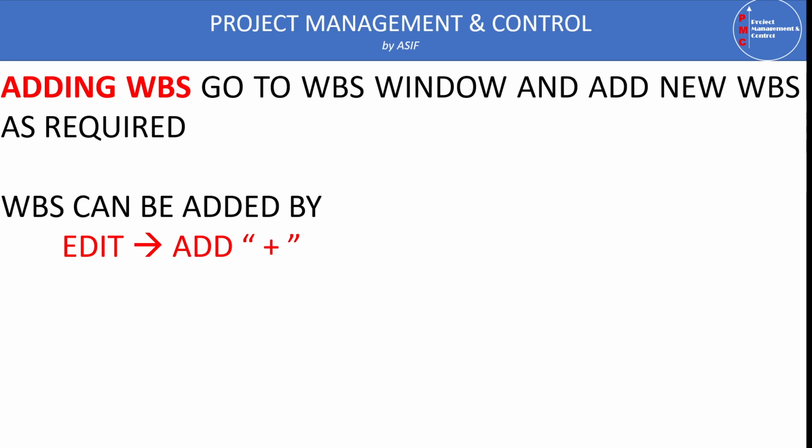We consider all these as your principal WBS, and under each you can define more. For example, engineering can be further divided into shop drawings, submission of the material, submission of the method statement, submission of the pre-qualification like this. And similarly, in the construction, you can define as per requirement, for example, substructure, superstructure, finishes, MEP, like this.